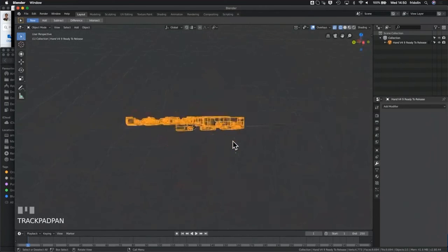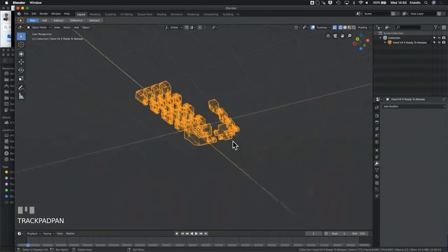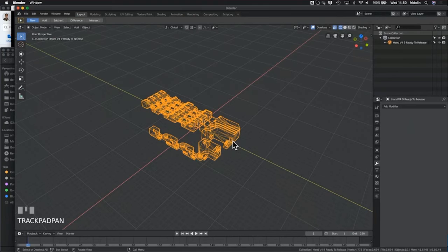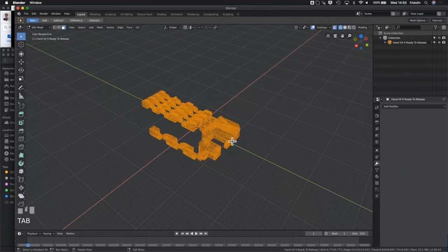So they've already laid it out for us as a single mesh, all kind of sitting on a flat bed ready for printing. But for what we're doing, we don't want to do that. With this hand selected, we're now going to separate it into a bunch of different objects rather than just have it all as a single object. So with it selected, we go into edit mode. Remember, we do that with the Tab key. Here we are in edit mode.